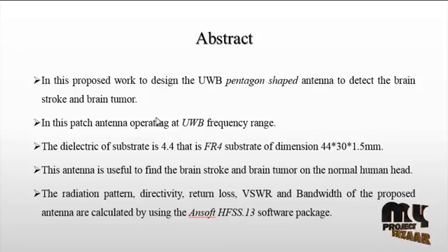In this proposed work, we design a UWB pentagon shape antenna to detect brain tumor and brain stroke. UWB means ultra wideband. This patch antenna operates at UWB frequency, a wide range of frequency, 3 to 12 GHz. That is the range of the UWB antenna.